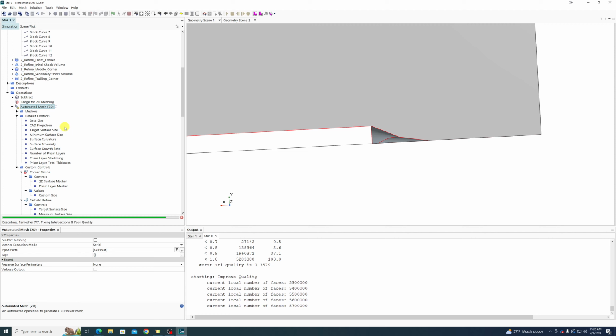But because this can only ever use one core, one logical computing thread, this is limited strictly to effectively the clock speed of the processor and the number of instructions it can execute per second. If it were doing a volume mesh, the more cores, the better. But for surface mesh, it's just how fast are the cores of the processor.